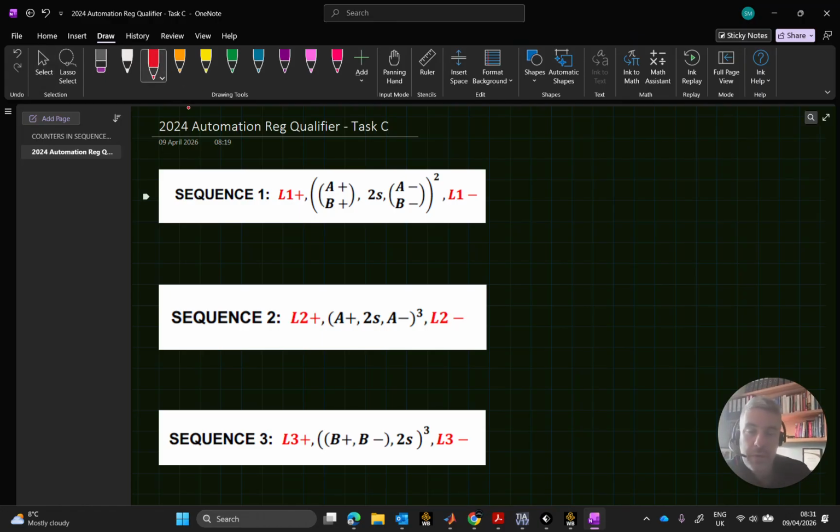This is the first thing you do, you write in steps. Now, lights, you can put lights in as steps, okay? So I would not do it like this, but I'm just going to show you. Like I say, the first thing we're doing in sequence 1 is step 10. Second thing we're doing is this counter, which is step 20. And then the third thing we're doing is the light going off, which is step 30. You can do it like that, and then these are going to be intermediary steps in the counter, which is step 20.